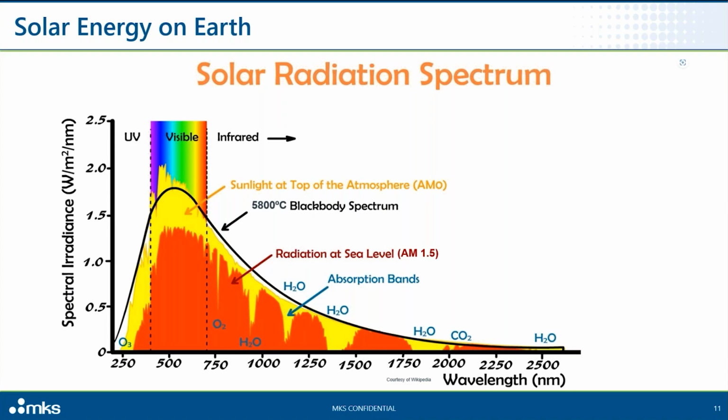So there are different air mass filters that can be used. The graph here is showing the air mass of 1.5. Basically, that's the ratio relative to the light coming down to Earth perfectly at a 90-degree angle, and the 1.5 represents about a 48-degree angle coming into Earth.